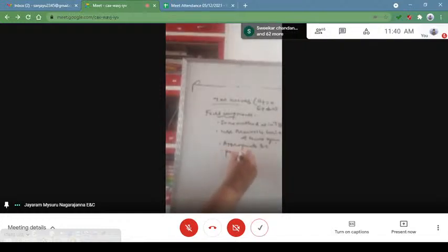Assume a product solution, and use separation of variables. If we use these methods, we will get field components similar to those of TE. We have already written some 6 components. In the same way, we can write the field components for TM waves.